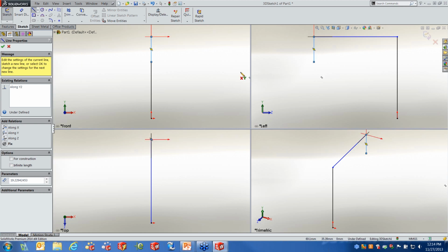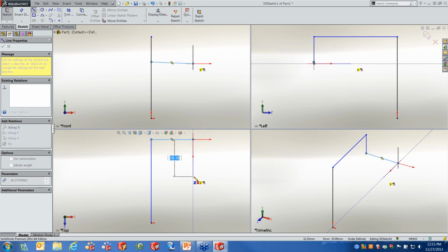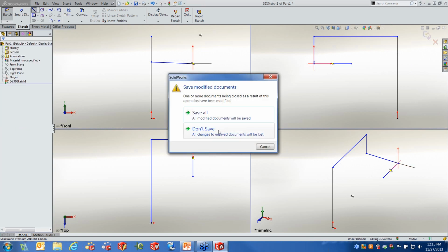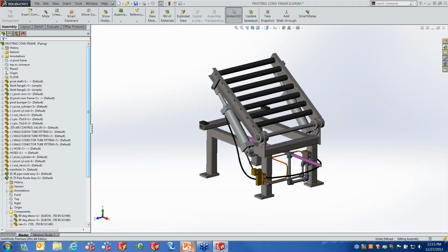Notice how things switch when I go from this viewport, it's YZ. This viewport automatically goes to the XY, and I can easily just come over in the X. But what's great is I can visualize it in 3D because I have the trimetric view in the corner, but I also have all the elevations, so now I can start to take a look at what I'm dealing with as far as elevations as well. Okay, so for routing, those 4 fundamentals, if it's something you're going to take on, I would brush up through the tutorials on those fundamentals with routing just to make sure that you have what you need going forward.